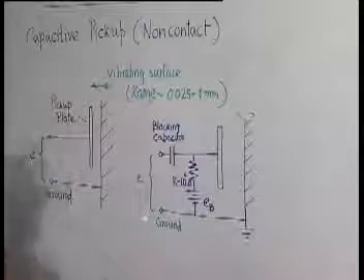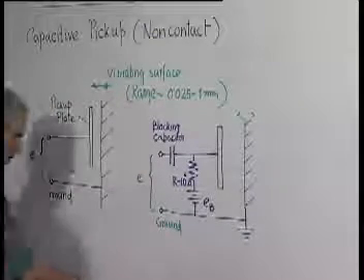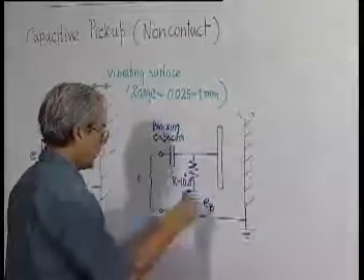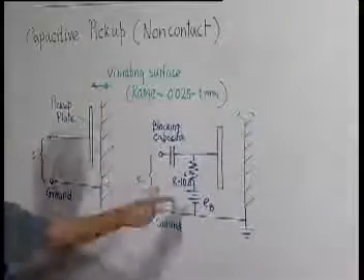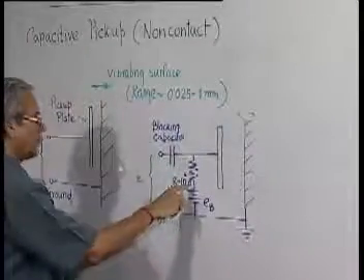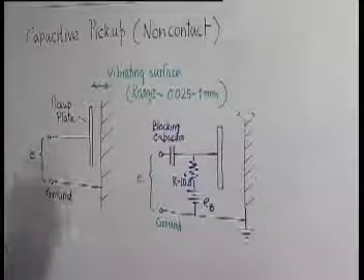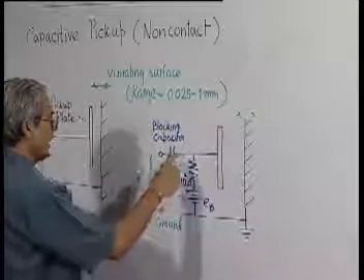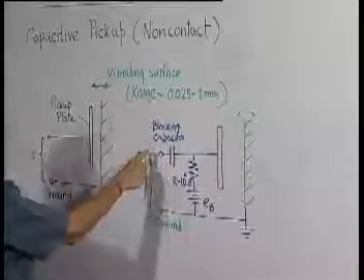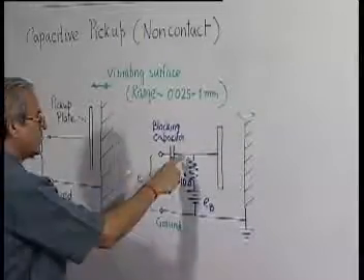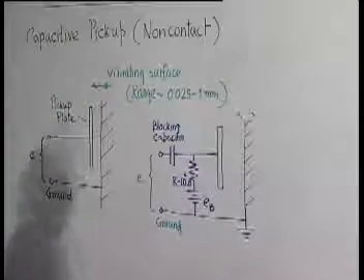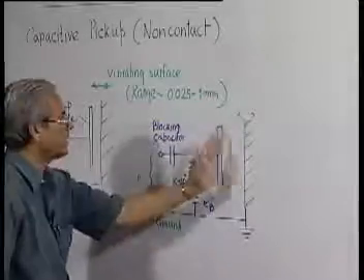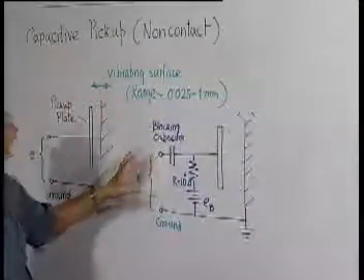so the circuitry which has to be used. The basic principle looks like this: we have to supply a bias voltage through the DC source, which is connected across this gap with the help of a very high resistance, 10⁶. And then, since the whole process is a dynamic process, we cannot just attach it, because then the instrument's impedance will affect the current through this. So what is done? A blocking capacitor is given here. So the variation in capacitance here generates a fluctuating voltage.